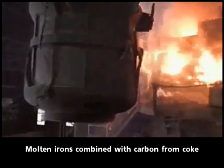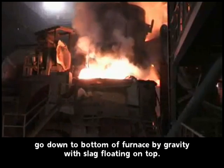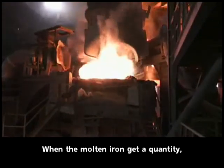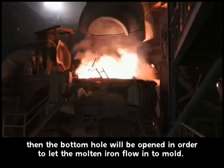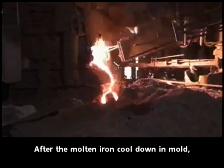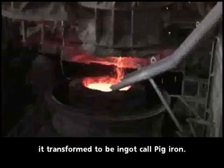Molten iron combined with carbon from coke goes down to the bottom of the furnace by gravity, with slag floating on top. When the molten iron reaches a sufficient quantity, the bottom hole is opened to let the molten iron flow into a mold. After the molten iron cools down in the mold, it is transformed into an ingot called pig iron.